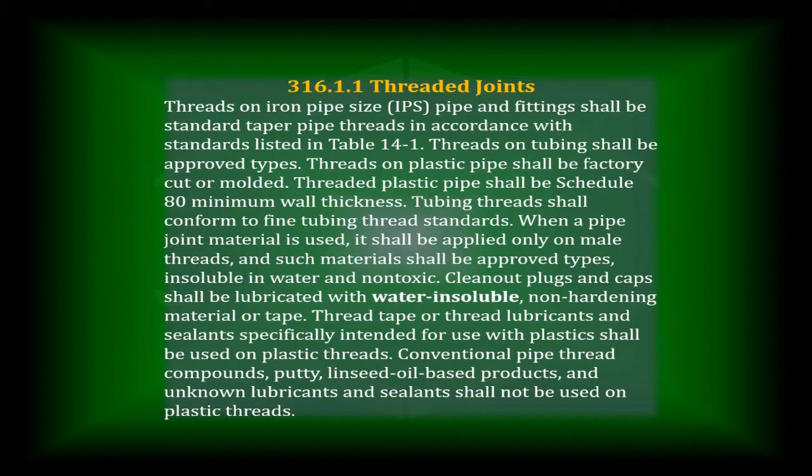Make sure you understand that if you're going from natural gas to LP, or from one of those to a potable water source, there may be different pipe dopes or joint compounds required, in case human consumption occurs, or because of the corrosive nature of the material that you're using it on.